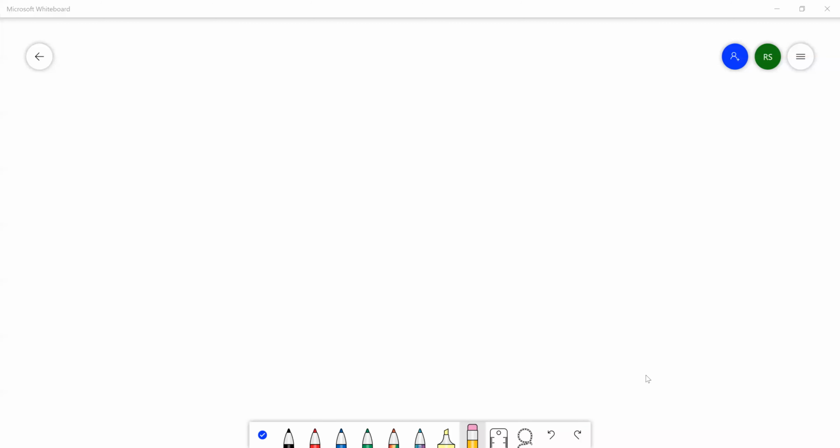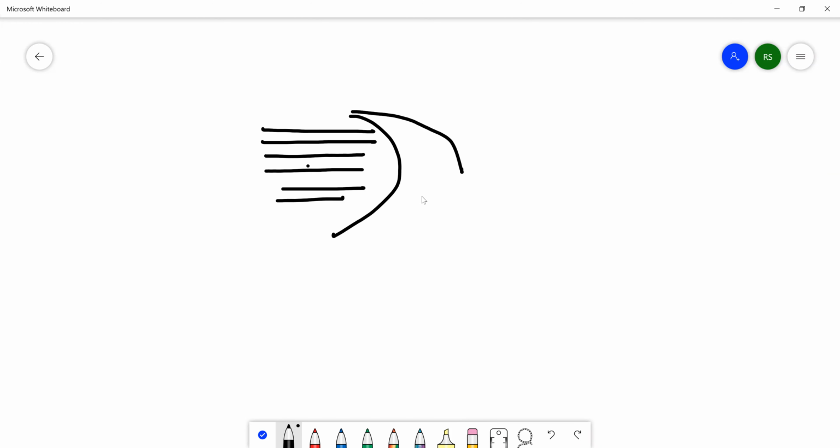Suppose I have a 6-input OR gate, which is the question I have now, and I want to convert it in terms of NAND and NOR. It's very simple. 1, 2, 3, 4, 5, 6. So it's a 6-input OR gate, and generally we can convert that into 2-input gates or 3-input gates.